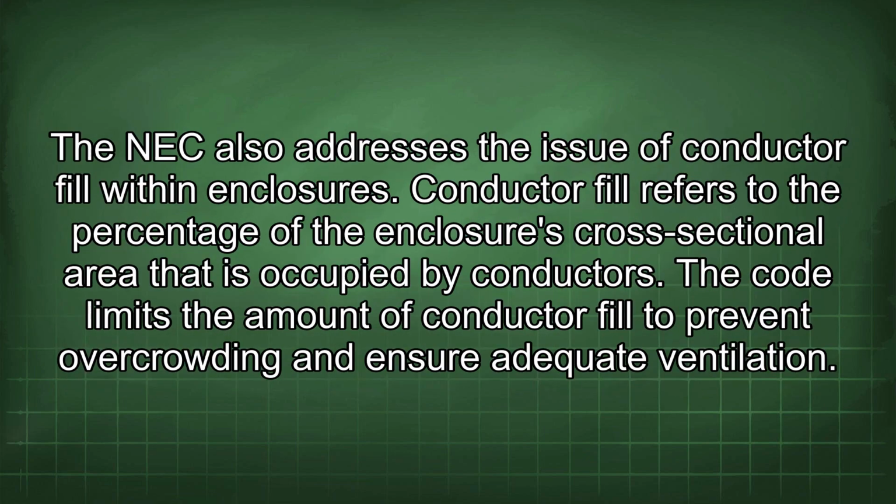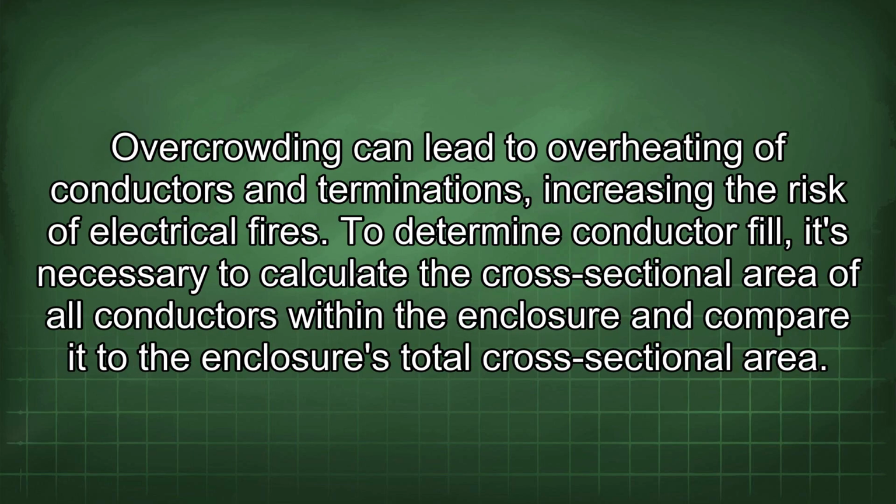The NEC also addresses the issue of conductor fill within enclosures. Conductor fill refers to the percentage of the enclosure's cross-sectional area that is occupied by conductors. The code limits the amount of conductor fill to prevent overcrowding and ensure adequate ventilation. Overcrowding can lead to overheating of conductors and terminations, increasing the risk of electrical fires.